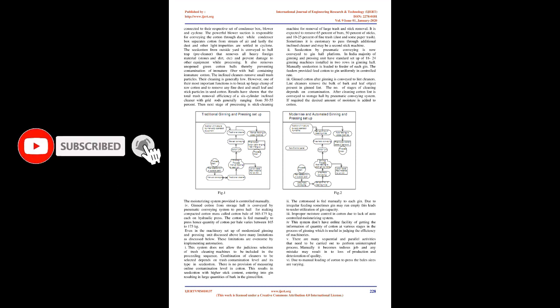2.1 Modernized ginning and pressing process. The entire process is a continuous process and the flow of cotton through the machinery is predetermined. The ginning machine is the heart of the ginning system where fibers are separated from seeds. The remainder of the equipment is used for conveying, especially pneumatic conveying which is preferred, humidifier and extraction of trash objects.